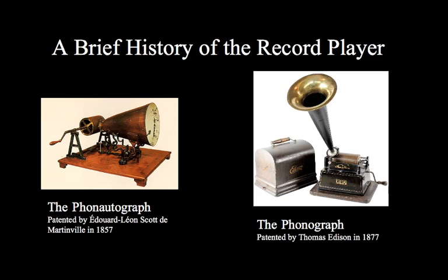So what's interesting here is that just like a microphone and a speaker, the microphone and the speaker are pretty much the same mechanism, only in reverse. This is exactly that premise. So you can speak into here, and those vibrations that excite the membrane here on the bottom would dig the needle into this cylinder, but then you could step away and we could put the needle on that same groove that you had just drawn with your voice, and I could start rotating again, and we would hear your voice come back to us. So the same mechanism that writes also plays back.